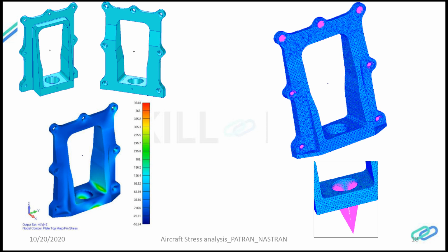So I was asked to study the load distribution within the fitting. Since my area of interest is only the fitting, I generated the mesh using the TET mesh. For the bolt connections, there are 7 fasteners that are attaching this lug to the aircraft galley panel structure.